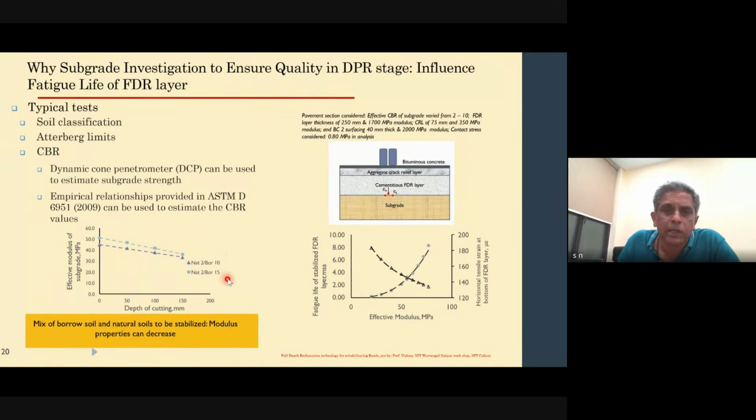On top of your FDR, you are going to add a SAMI layer, which carries about 6 millimeter thickness. And on top of that, you have a 40 mm BC. So if you want to estimate the finished road level, it is going to be the reduced top level of your FDR, which is 101.23, plus the thickness of your SAMI layer plus the thickness of your BC. So the final finished level after construction would be somewhere around 101.28 meters. That is what the final level would be.